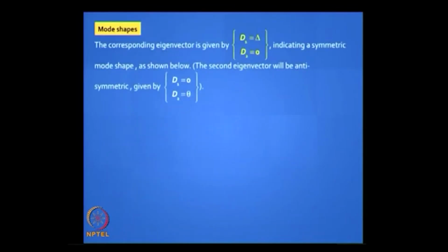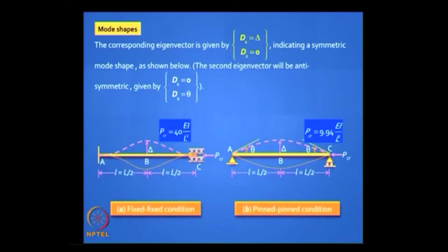And if you want the mode shapes, you get them also, except that when you have two elements you just get one delta. It does not really help you, but still you can try to plot it. You do not know the curvature of those lines, right. So we are guessing that it is going to look like this because we know the slopes have to be 0 at the two ends in case A. But if you really want to generate that mode shape more correctly in a case you did not know, what would you need to do?